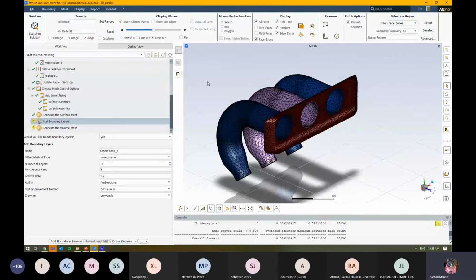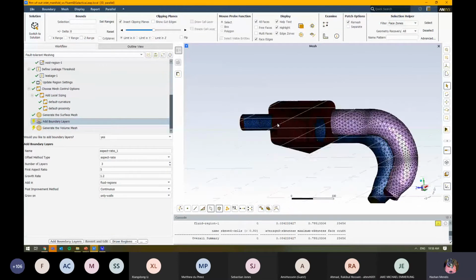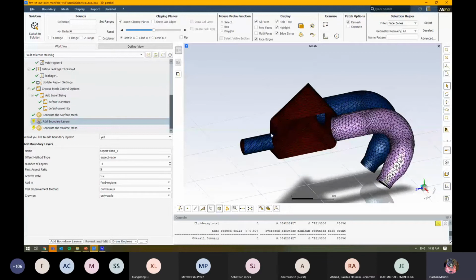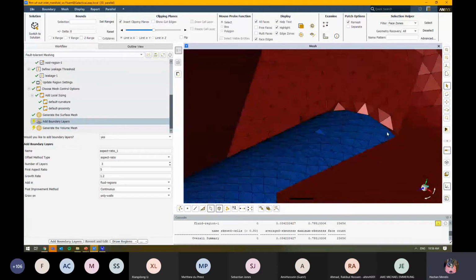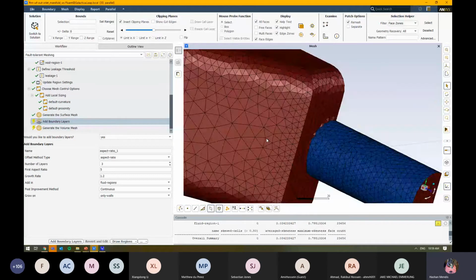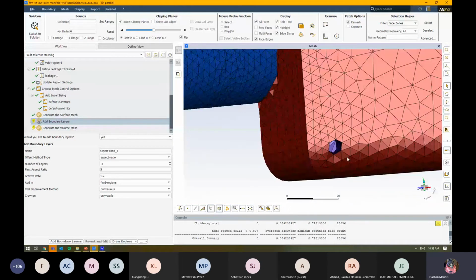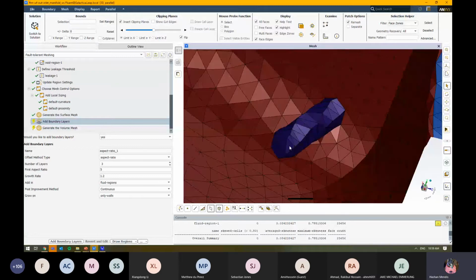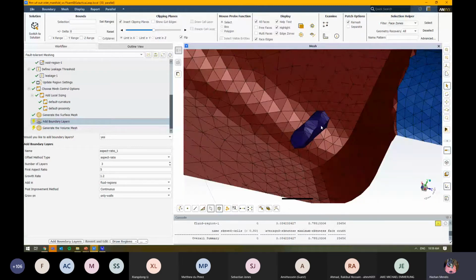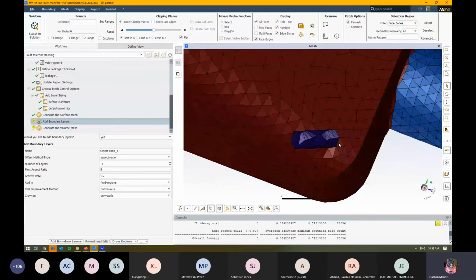Awesome. So it's generated the volume for us. Right, so it's removed all those other solid components and then generated that volume for us. You can kind of see where you've got these different components and how it's stitched that mesh together as well. One of the things you'll notice though, it's picked up this volume here. This is exactly what I wanted it to do, so it removed that surface in there, but it's very, very coarse around that region.